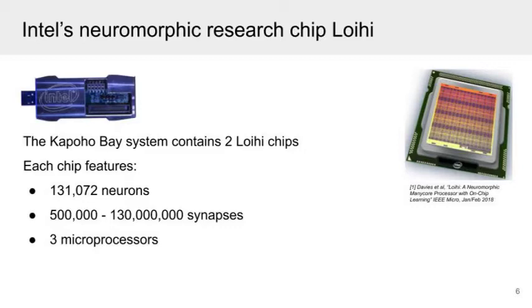In this work, we simulated our spiking neural network on a Kapoho Bay. The Kapoho Bay system features 2 Loihi chips, but we only used one of them. We used the USB interface in order to reduce the development time of the system, but in order to increase the communication speed and therefore the speed of the closed-loop response time, a low-level interface could have been used.